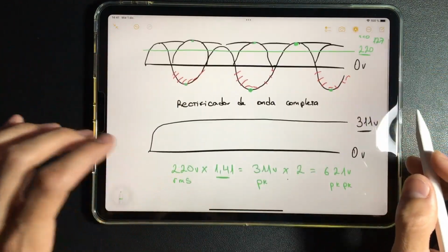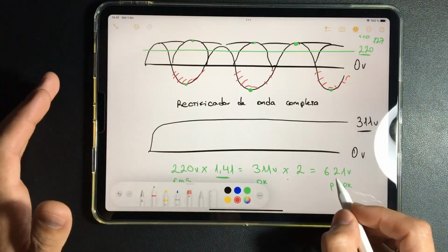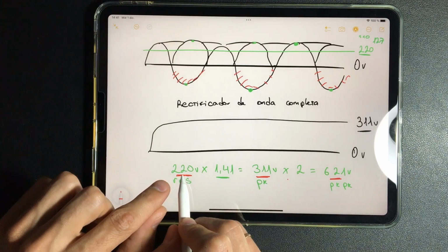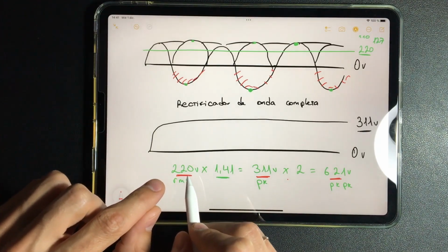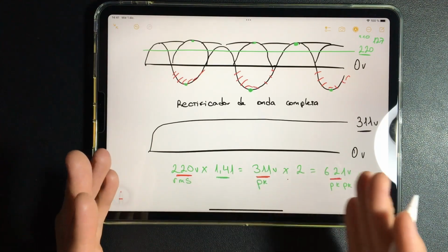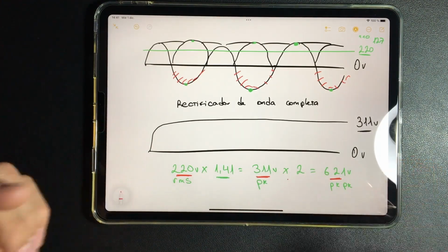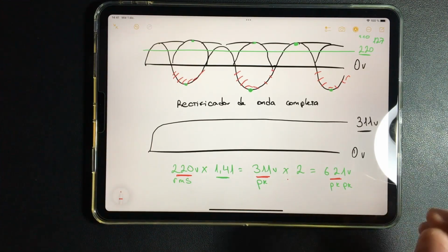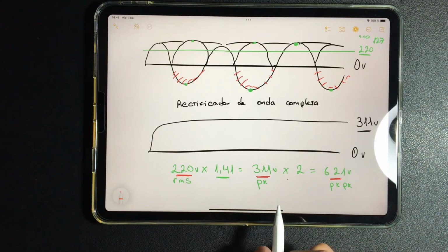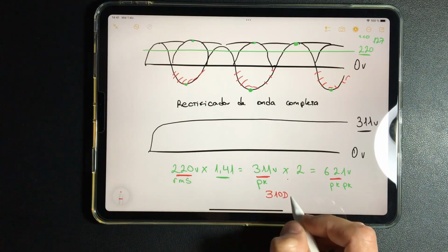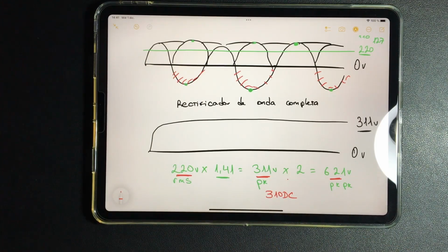All these voltages, which are new to many, are voltages that we have to get used to. If there are 110, they have to change this data to 110 or 127. All this is managed with an inverter. In fact, if you have already disassembled inverter equipment, you will have seen that motor compressors work with 310 DC as long as you have 220.